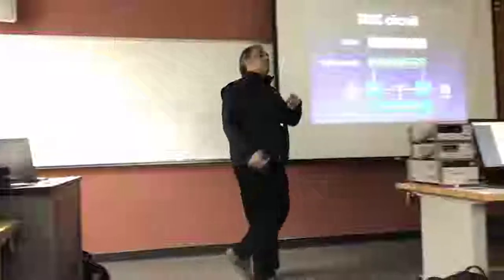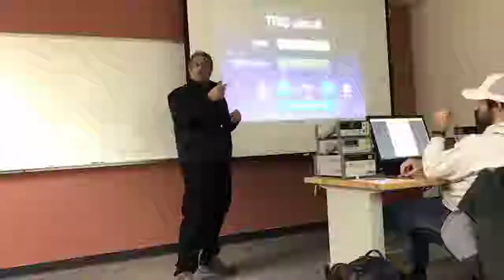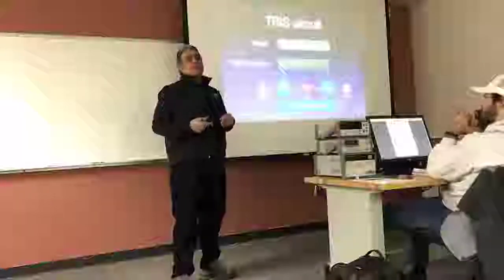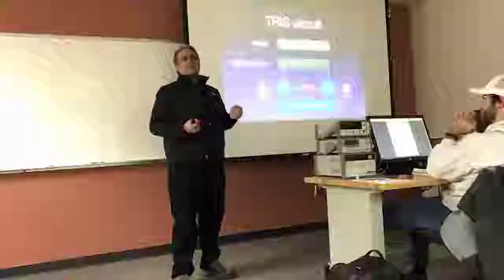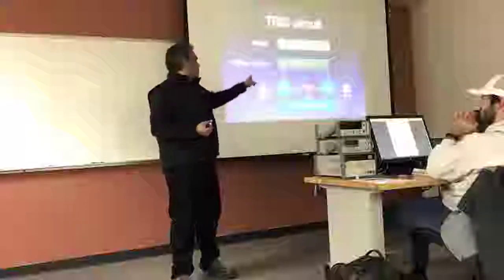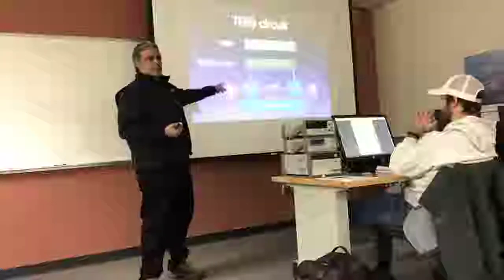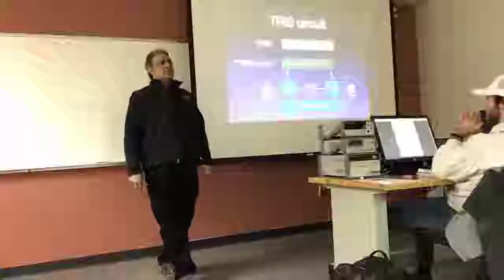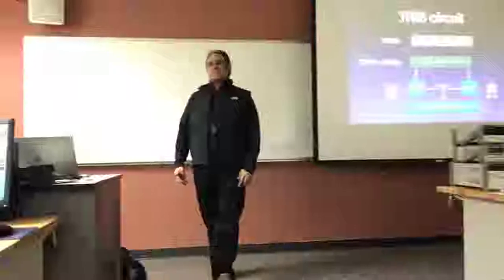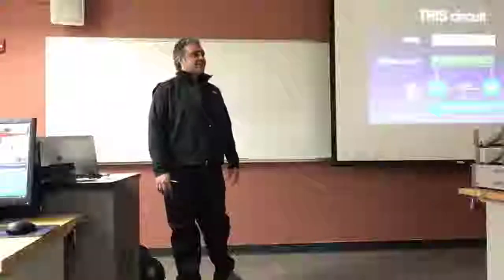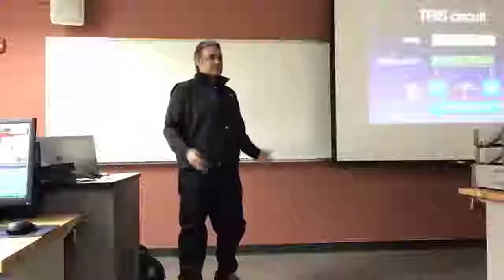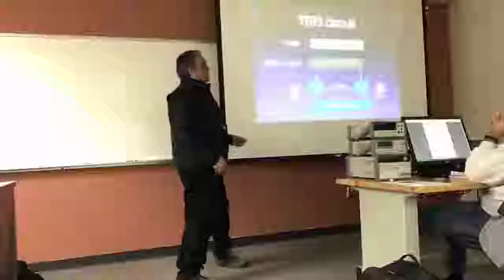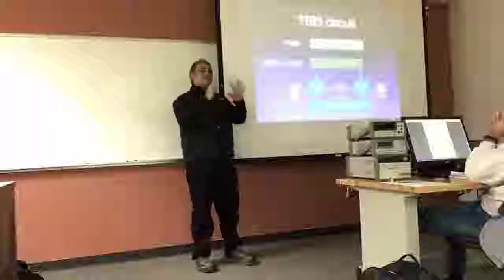Well, let's think from the Arduino world. From the Arduino world, there are some registers called DDR. And so the DDR register is what the TRIS register is here. They just changed their names because they're competitors and they don't want to just have the same name. It's dumb. They should have called it DDR, but they call it TRIS. But that's the data direction, right? It's all about data direction.